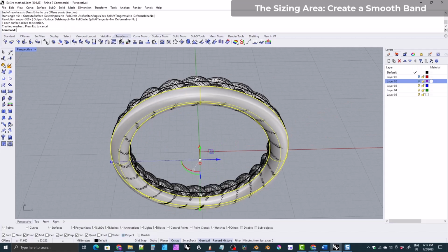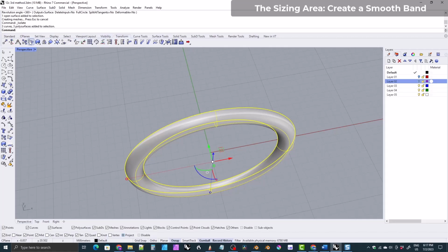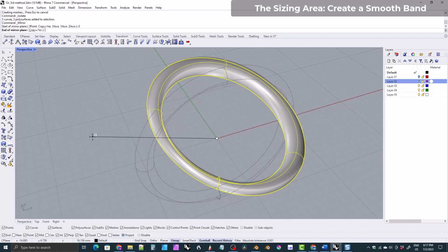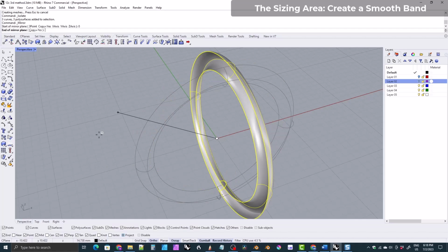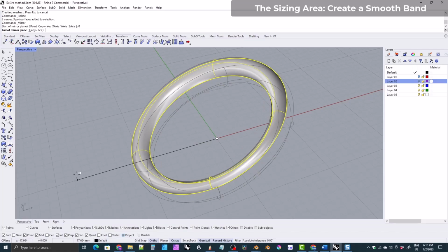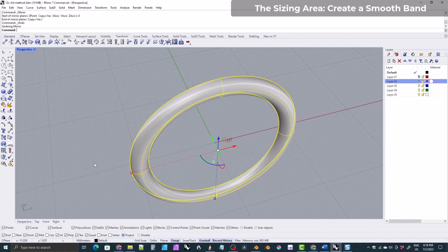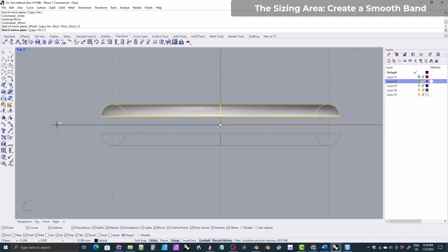I'm going to isolate that, so visibility and isolate, and then with it selected, I'll go to transform and mirror, and I'll mirror it this way. So 0 for the center of the world, hold down Shift and pull out along the x-axis here. So even though the red line is over here, I'm still in line with the x-axis. Holding Shift is going to lock me into 45-degree angles. So I'm just going to pull out this way and click. And that mirrors it over like that to the other side. If you have trouble with that, do it in, say, the top viewport and mirror it up there. That might be easier, okay?